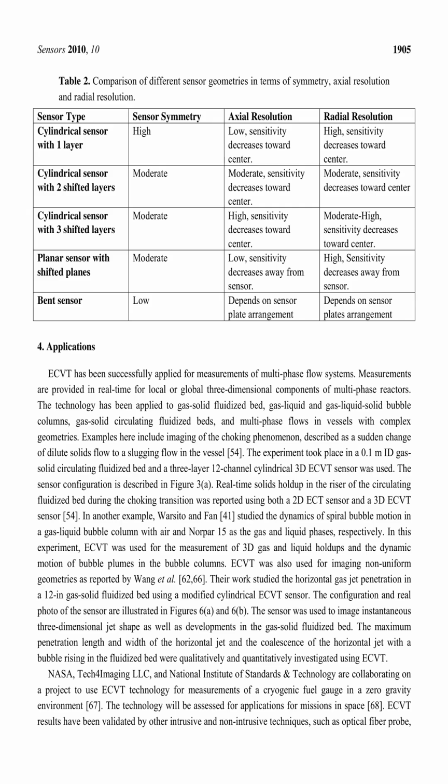Applications. ECVT has been successfully applied for measurements of multi-phase flow systems. Measurements are provided in real time for local or global 3-dimensional components of multi-phase reactors. The technology has been applied to gas-solid fluidized beds, gas-liquid and gas-liquid-solid bubble columns, gas-solid circulating fluidized beds, and multi-phase flows in vessels with complex geometries. Examples here include imaging of the choking phenomenon, described as a sudden change of dilute solids flow to a slugging flow in the vessel.